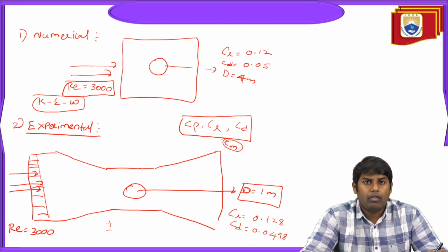When you are conducting the experiment on the day, is it exactly 1 atmosphere, or 0.98 atmosphere, or 1.1 atmosphere? Those values also we need to check. Whatever instrument values we get from the wind tunnel, whether they are exact or not has to be evaluated. So we have errors associated with the experimental setup, and errors associated with the numerical setup.